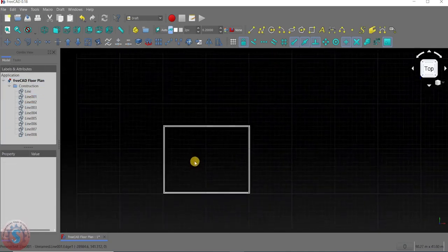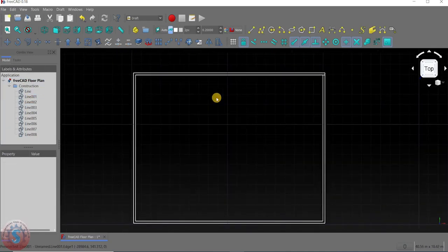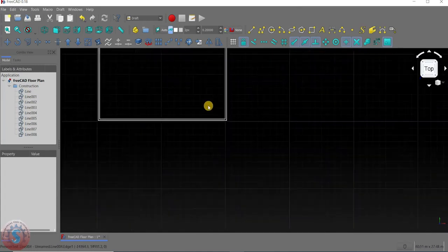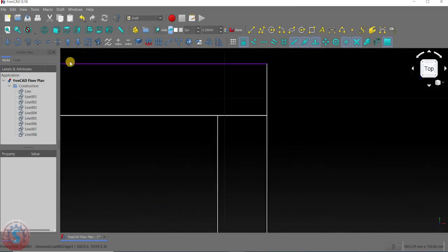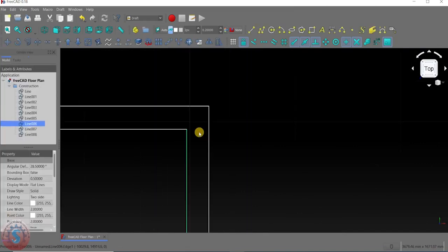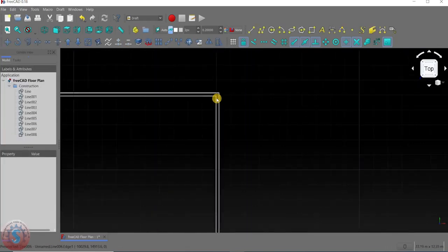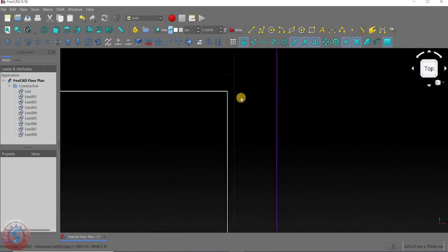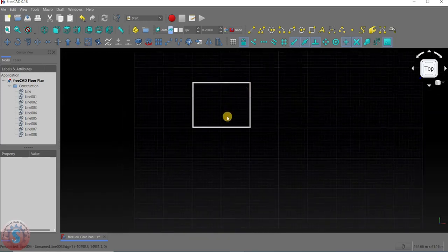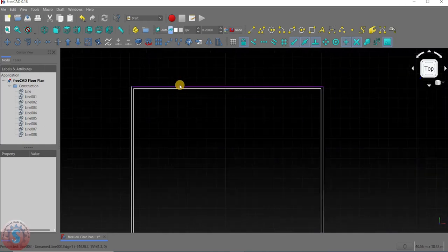See, the wall is totally created by using the offset command, move command and the trim command. This is basically the explanation. You can observe some of the lines are there. Here also I trim this and select this line. You can observe that when using the trim, the object you are removing is highlighted as green, up to the endpoint, and it is highlighted in pink. You can observe like this. The trim option is working well. You can observe that the whole wall is created.